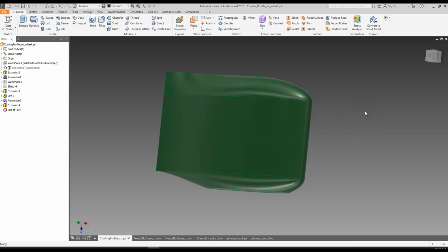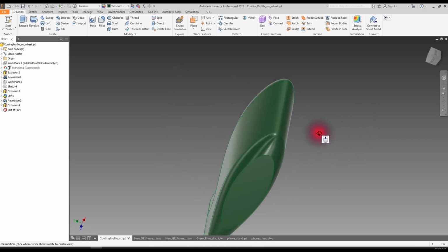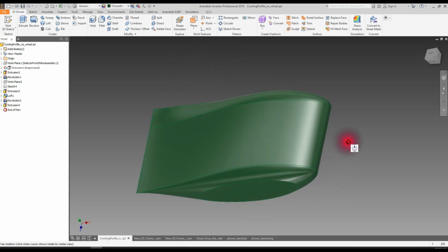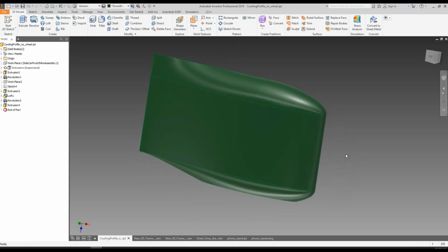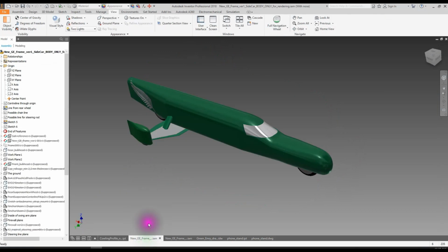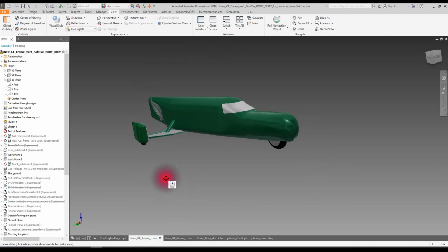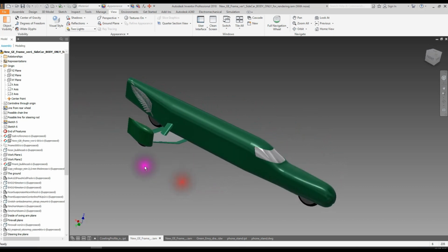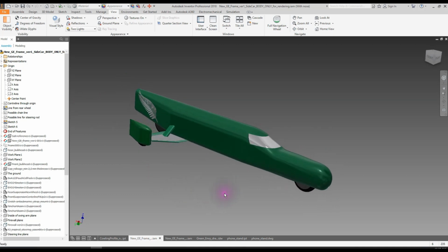So we have the part files, the .ipt, which is an individual part such as this wheel cover here for my racing motorcycle. So that one is created as an individual part. Then I take these parts and put them together in an assembly. So here's an assembly of my whole next motorcycle, the Green Envy. And you can see this is the wheel cover that you just saw in the part file, and this is an .iam file, which is an assembly.